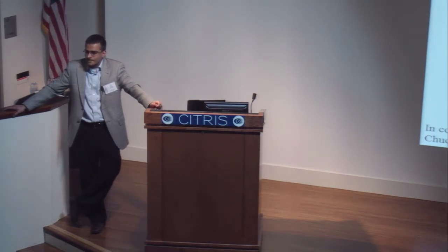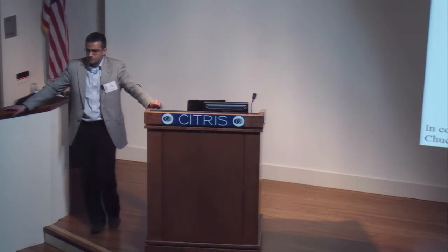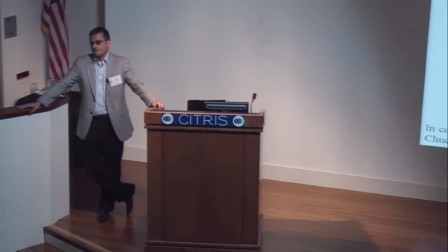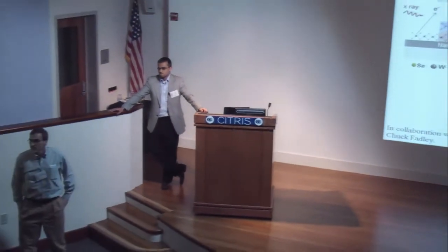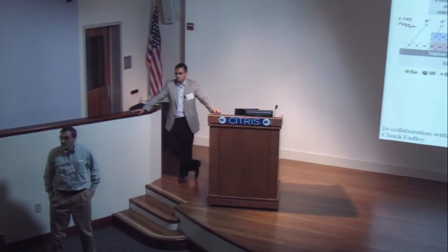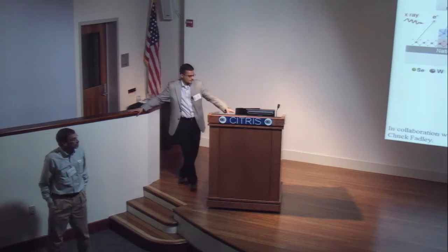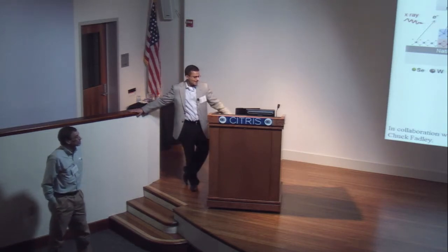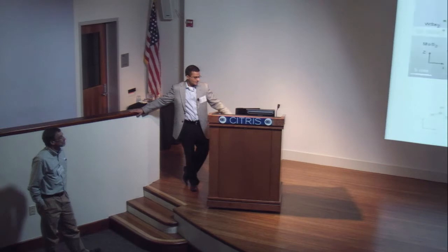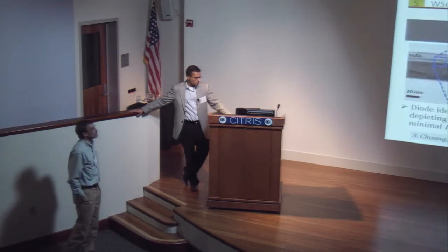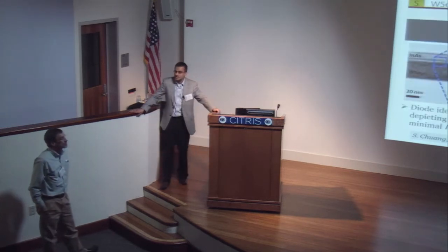Great, thank you. So a follow up on your indium arsenide and tungsten diselenide diode. Your current density is like microamp per micron squared. So what do you expect? I'm just wondering, that seems a little bit on the low side for practical applications. So far we don't know what is limiting the current density here.